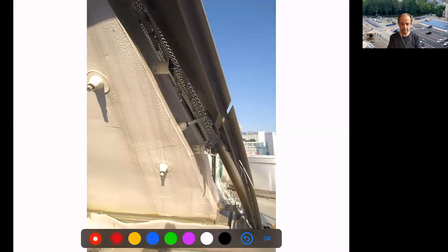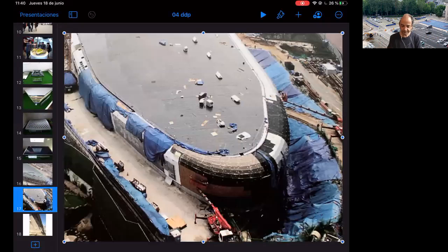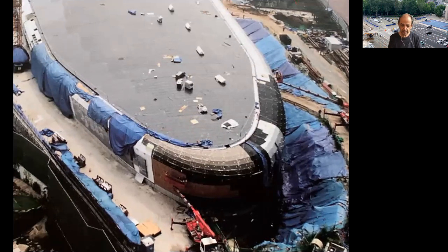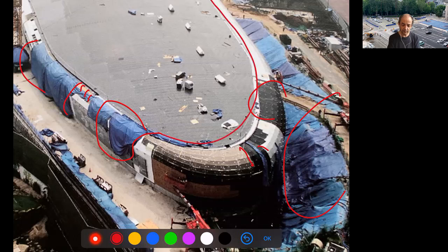One thing, I would go back to one slide. We are almost finished. You see this blue thing here, also in the excavation. If it rains, things get messed up. So when you have some sensitive element like this timber finish, you protect it in case it gets wet or dirty, because to apply this vinyl and the paint and the layers, it needs to be clean. You don't want to accumulate a lot of powder. You see also the waterproofing of this big area.